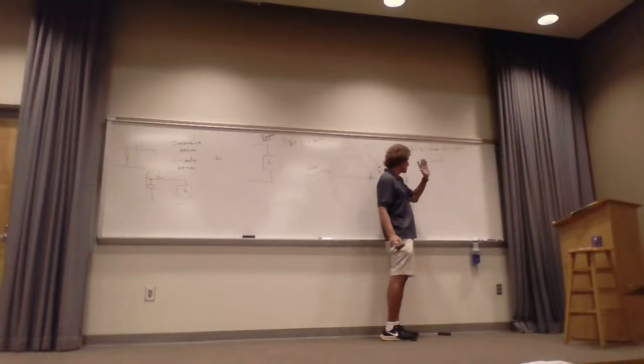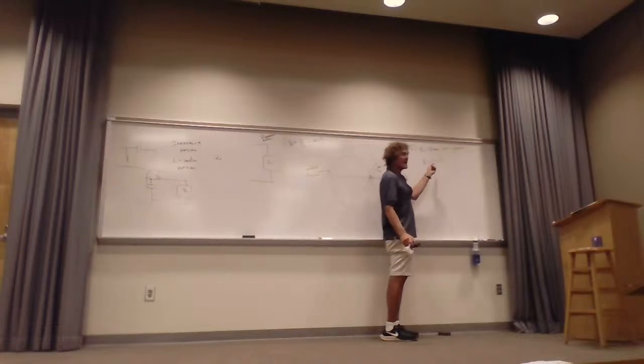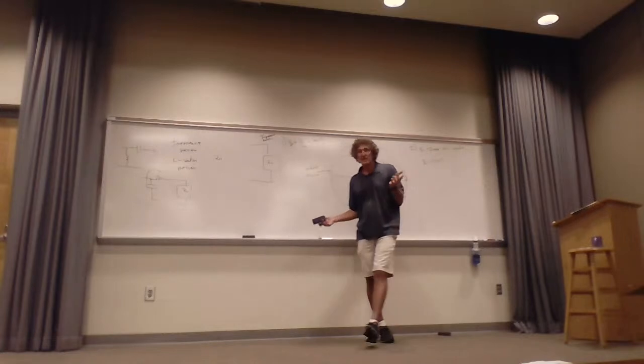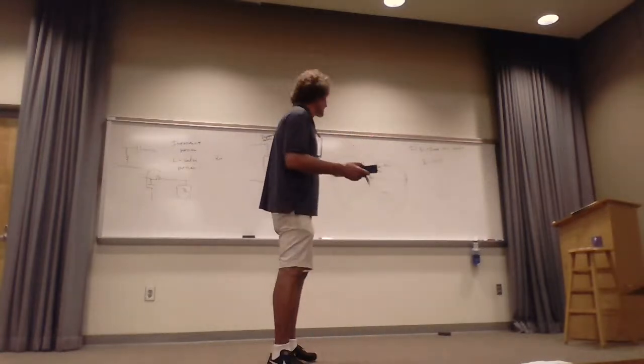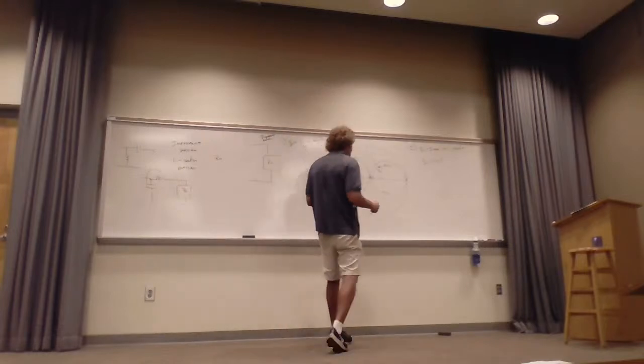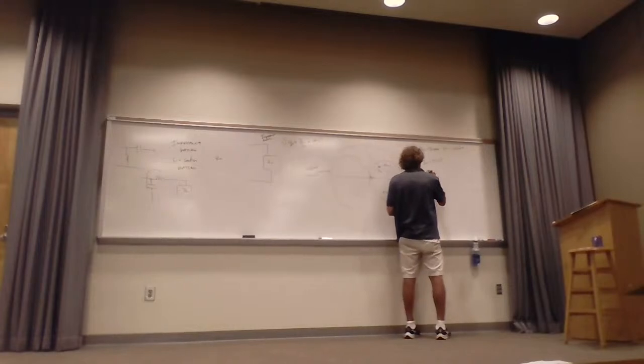My goal, when I'm done with everything, is to either normalize Y or normalize ZL to a value of 1 and only 1, right? That's what impedance matching is all about, right, guys? So no matter what I add in series, it does no good. Follow me? I can't get it to a value of 1. So I go to the admittance domain. ZL is inside the arc of the 1 circle, so I immediately go to YL, and that's going to be 1 over ZL.